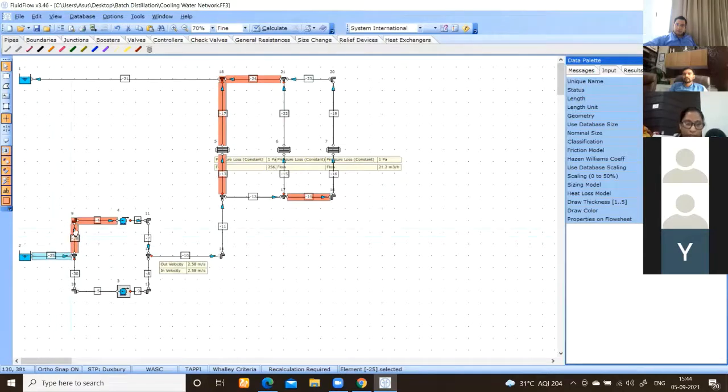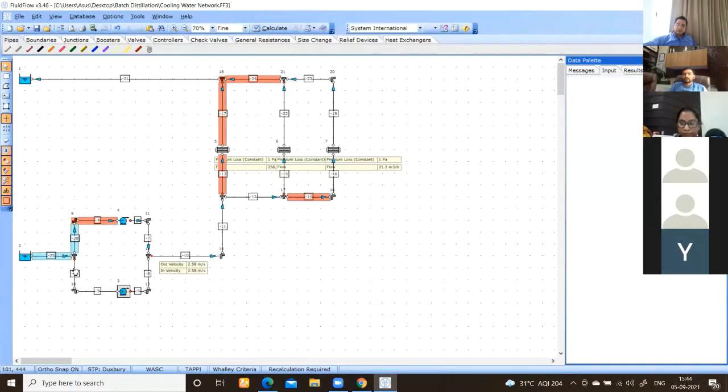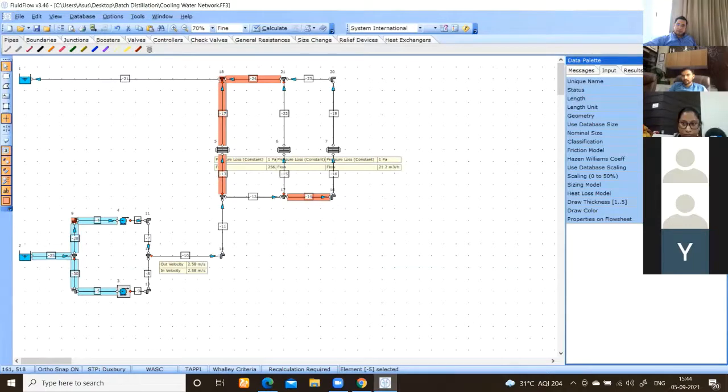All right, so this size we can put as 12-inch for the suction side. Select all the pipes in the suction. Yes, so 2 meter length, 12-inch, schedule 40. See, length you can put 10 meters. Okay, enter, again type 2 meters. Okay, then this you make 6-inch, schedule 40. Then again change to 12-inch, schedule 40.